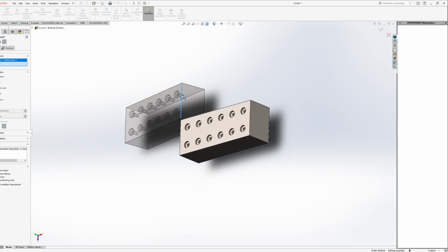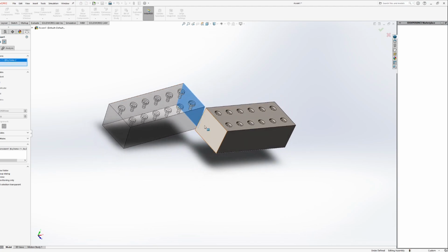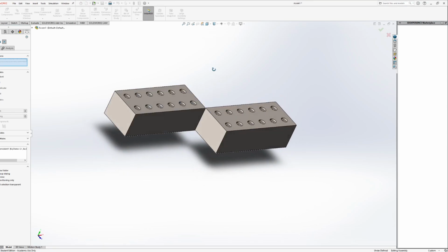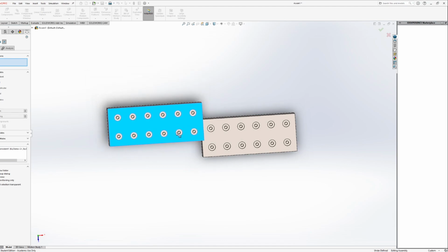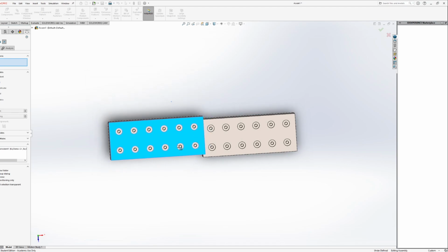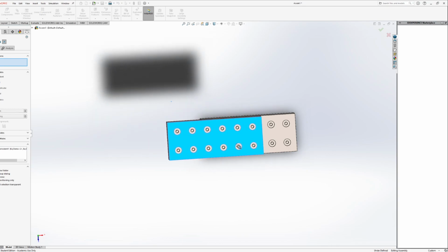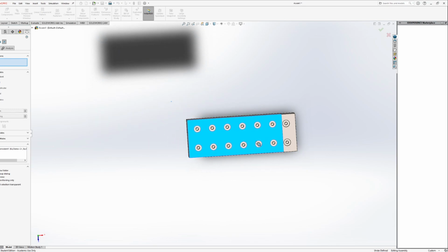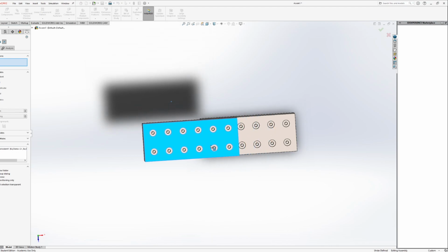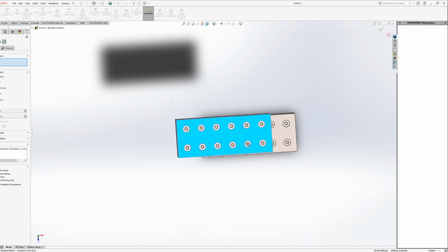Perhaps I wanted to do, not an edge again, a face mate. Now, if I mate these 2 things together, they are just moving right against one another, and it's super hard to see when I move it like this. If you're paying attention to the shadow, it's not actually moving further to the right in the X direction, it's moving upward, which is kind of stupid, but that shadow is indicating that you have something that is higher up now.